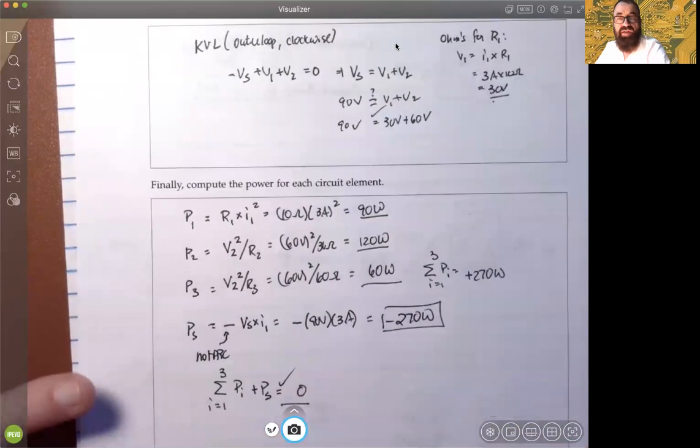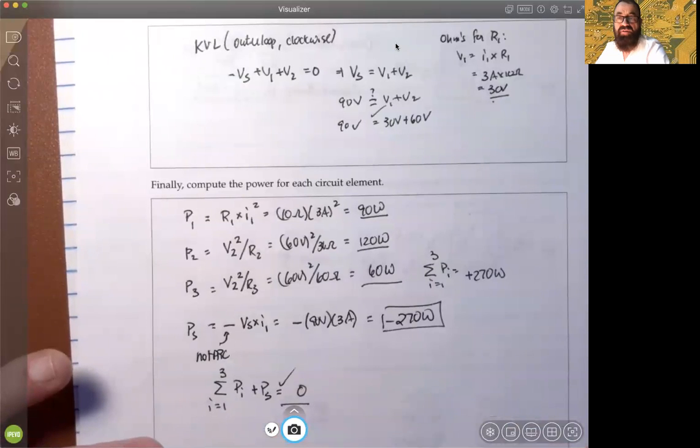So the goal of network analysis at this point is to exploit series and parallel equivalents, to roll back each stage of the reduction so that you can determine the appropriate voltage or current that you need for every single element. Remember, in the case of parallelism, the voltage at an equivalent, if it was generated from parallel resistances, gives you the voltage you need for those.